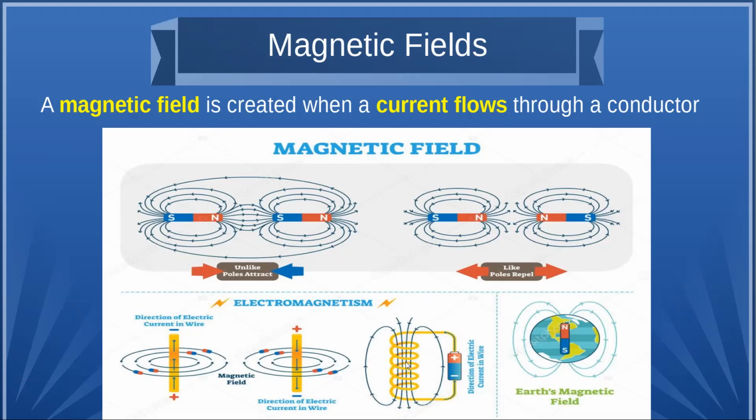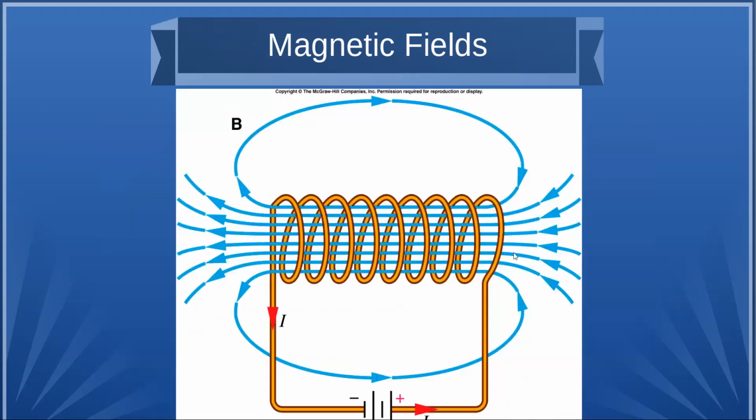In other words, it acts like a magnetic conductor. So it's things like iron or the ferrites and things like that, which have very low magnetic resistance. So this is just showing, again, with the current going through the coil, the concentrated magnetic lines of force. You get a little bit on the outside, but most of it is in the center.